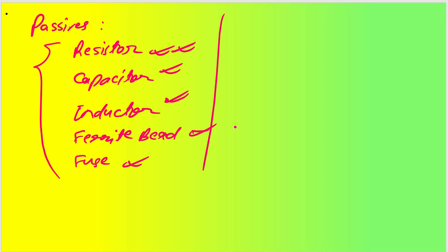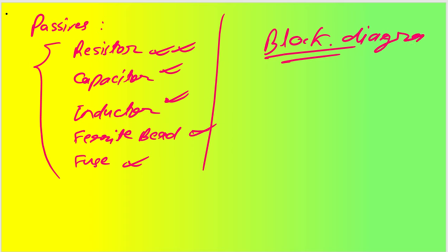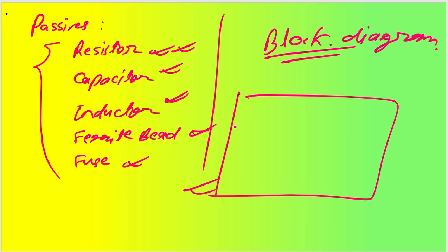Basically, you will first have the block diagram, based on the need. Then for each of the various peripherals you will select the components for the respective functionalities, and each of those components will have its own application circuit or reference design. All those application circuits or reference designs will be clubbed together to make the complete circuit, and after reviewing it you can go ahead with your PCB layout design. So this was a rough explanation of how to start designing a circuit for your various applications.